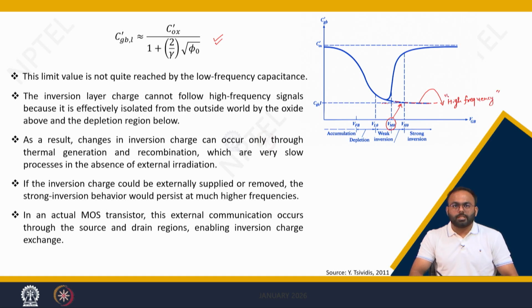Whatever we have discussed was for a quasi static or steady state condition, meaning you applied a VGB, the VGB will add some additional charge into the gate and the gate will cause a negative charge into the surface. So, this process takes time and hence you are giving time to the charge to respond. That is why you have a CV characteristic like that.